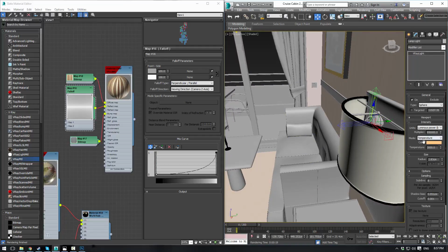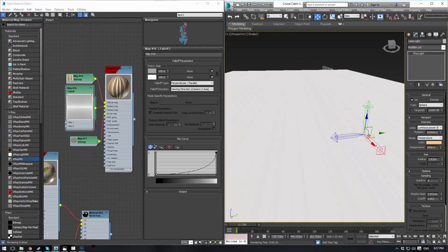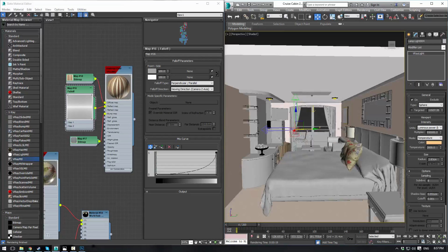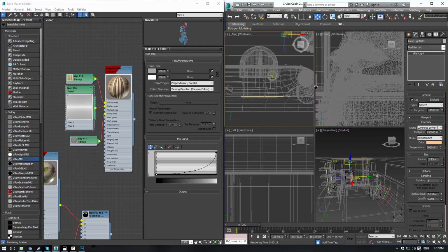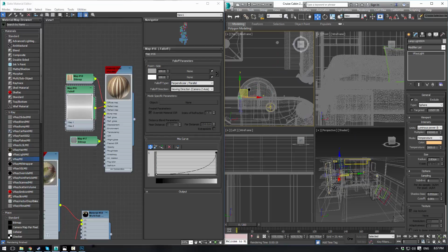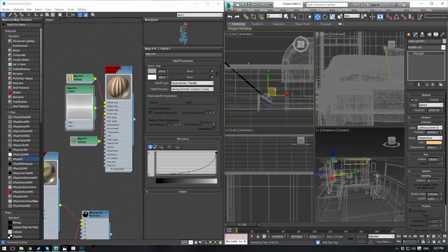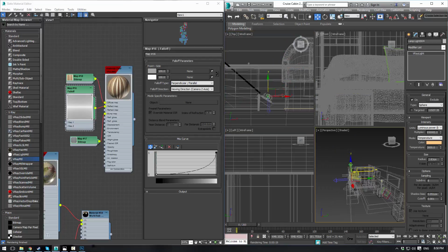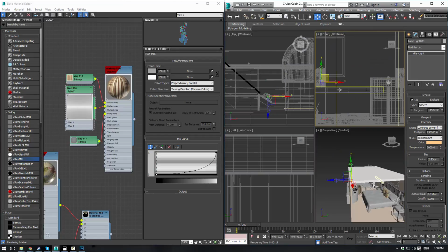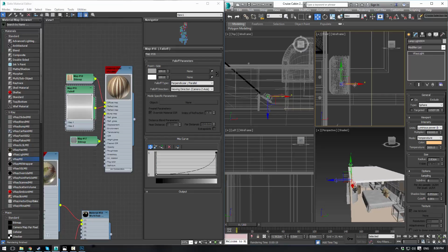So these are just simple V-Ray lights. I put the temperature at about 3000. The luminous power is pretty massive because my scene scale is a little bit off, but I'll work on that a little bit later. For now, I'm just using it to get sort of a general idea of the color for everything. Oops, watch out there. And let's just put this in here, and let's see. Height looks good.